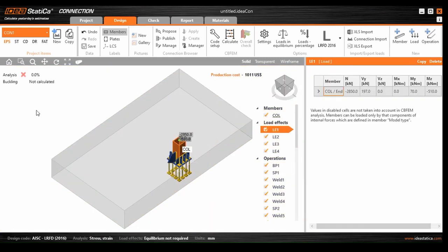Well, now click on EPS here. It stands for elastoplastic analysis. ST means stiffness analysis, and we get to this part after we finish EPS analysis. So first click on EPS here, and then come here and click on calculate.